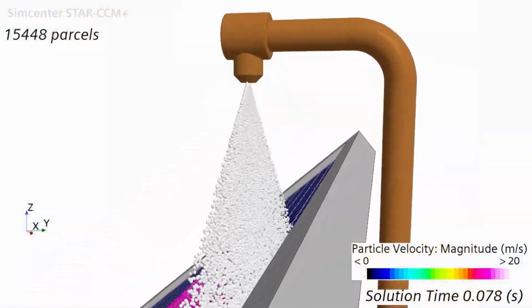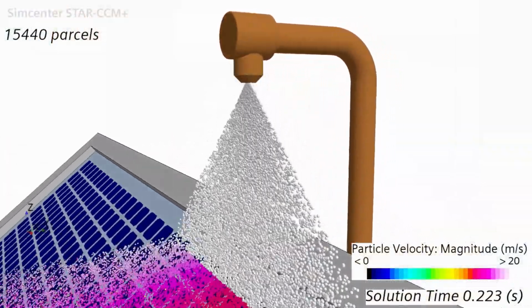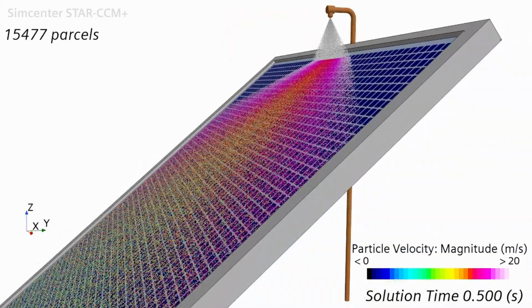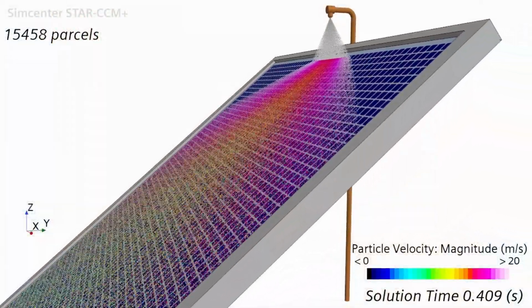For the second contribution of today, I will change the topic a little bit and jump into the Lagrangian world of SimCenter StarCCM Plus, because I want to introduce a new type of injector which is released, specifically the flat fan nozzle injector. This technology leverages the LISA breakup model, which stands for Linear Instability Sheet Atomization, and is a type of injector needed when there is a requirement for a flat and uniform distribution of particles that need to be injected, and is really enabling a wide